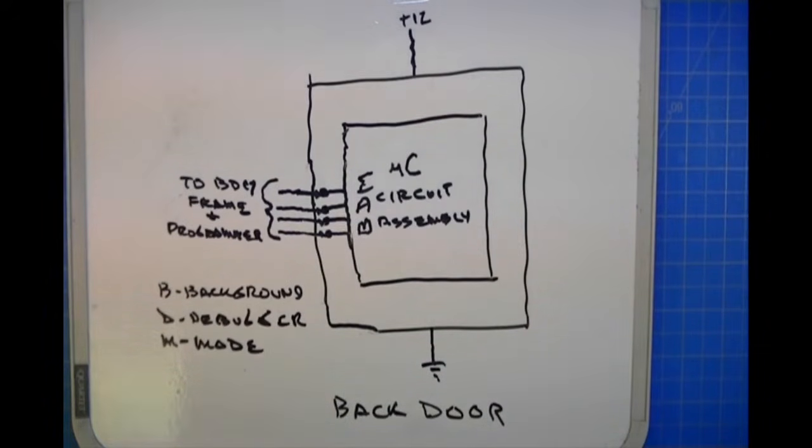Anyway, that became kind of encumbering when it came to debugging larger pieces of code, plus it used more pins. When you design a microcontroller, you want to be able to use all the pins on the outside of the package to do control things. You don't want those pins dedicated to uploading programs into the microcontroller. You would like to test your program with all of the functional pins of the microcontroller.